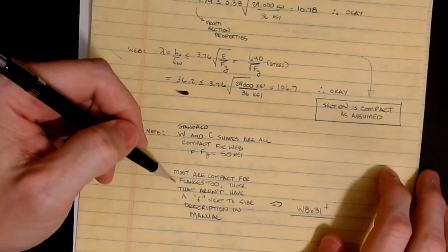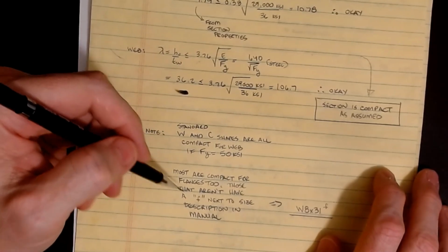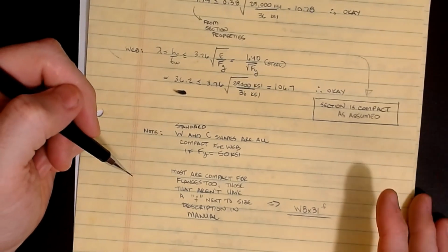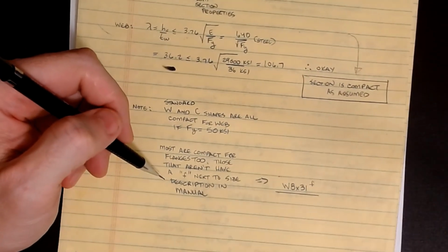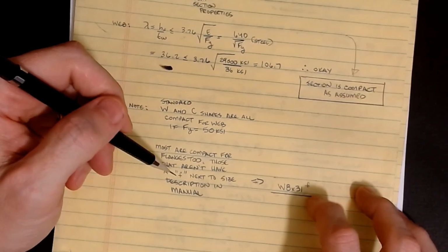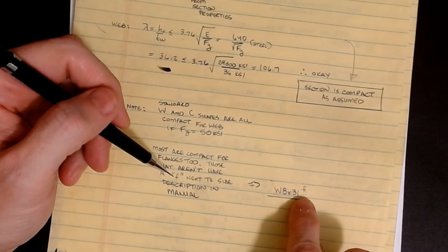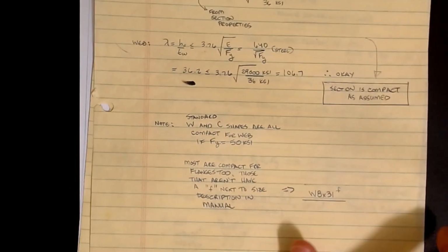Okay. The other one is that most flanges are compact as well, except for the ones that have that little F that I just showed you. So if you choose a beam that has an F on it, you know that you're non-compact, or partially compact, I guess is the right word for it. And you're in region 2. So you got to be kind of wary of that F that's sneaking around on you. Okay. All right. So that's how we do these types of example problems.